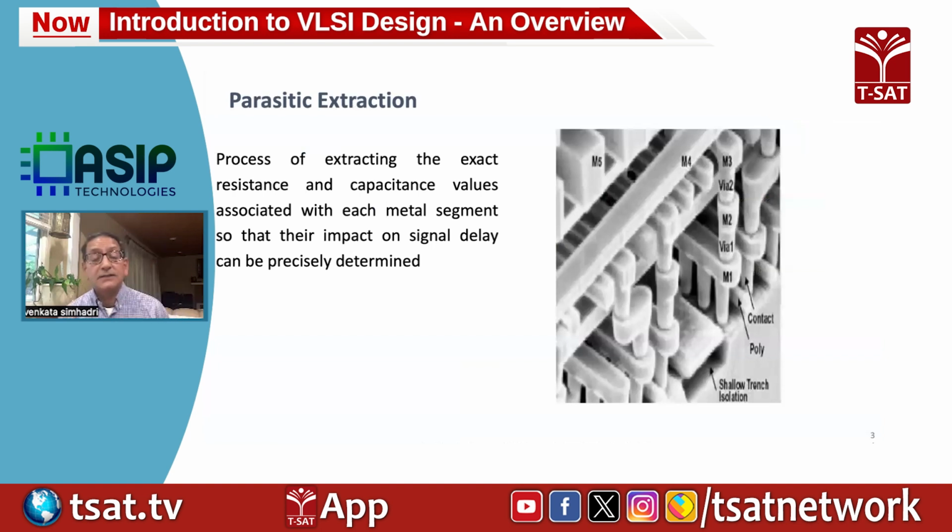And so here, let's say you start with a gate level design. Functionally, it's looking good. But when you actually take the design and convert that into a physical format and connect the cells using metal layers, the metals will be introducing some parasitics between the gates.